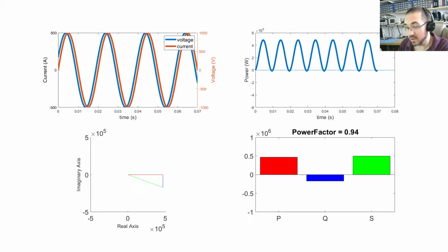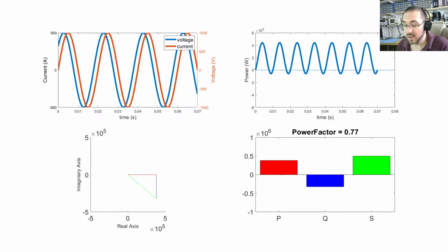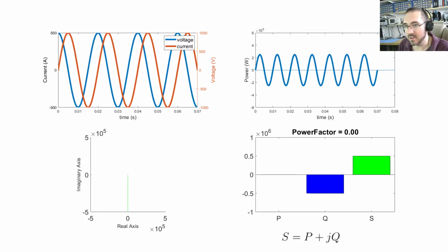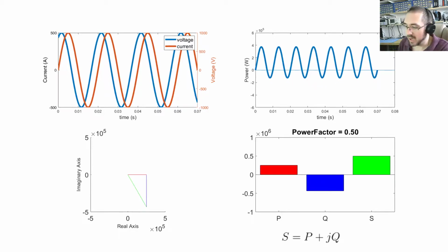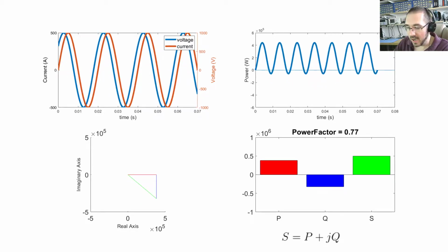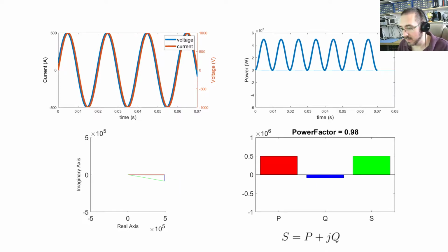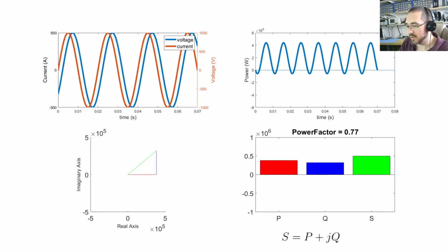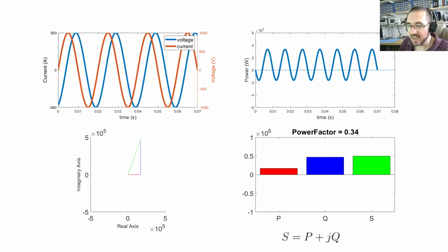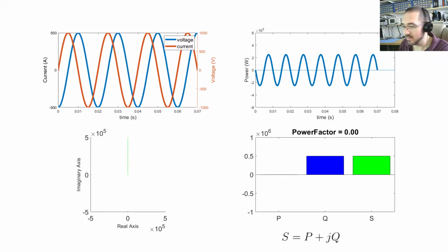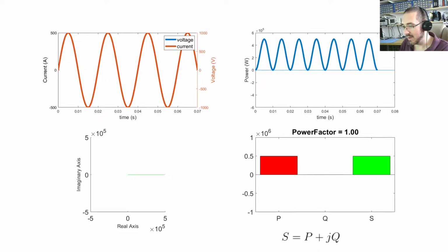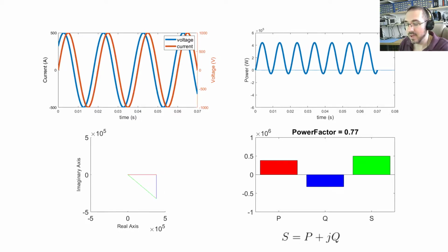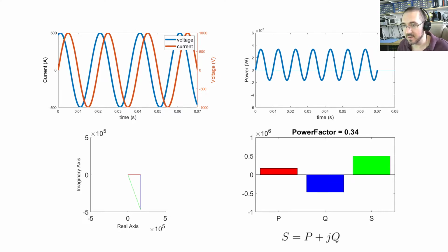And we can call this P and Q. The combination of both of these types of power, because they both exist simultaneously on a circuit, is called complex power. And it combines as P plus jQ. And this is why the analogy between, if you look at the interaction between P and Q, it's similar to the interaction between up and sideways in Cartesian geometry. It doesn't matter how far up you go, you don't go sideways at all. So in a way, these are completely separate things.